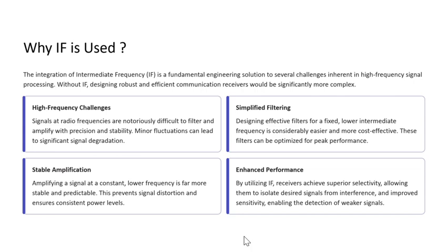Why is IF used? If we try to directly process the high frequency signal, then filtering becomes difficult and amplification becomes unstable. So, IF is used to solve this type of problem. Using a fixed IF helps in easy filtering, stable amplification, and better overall receiver performance.